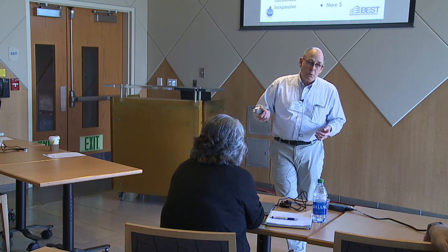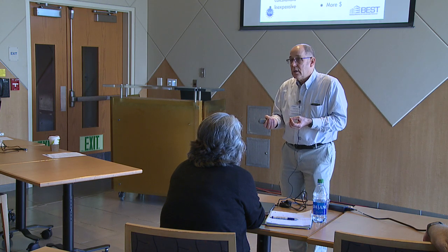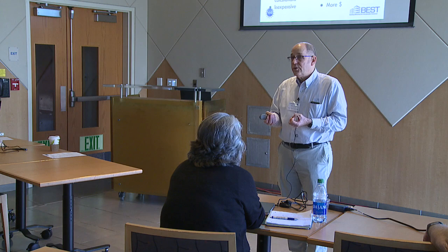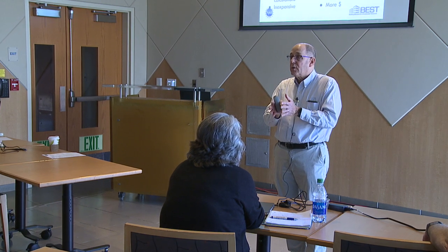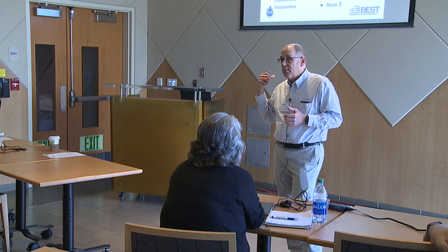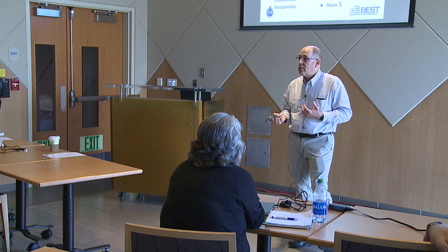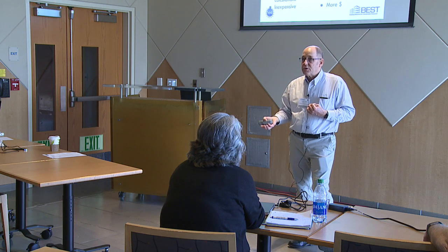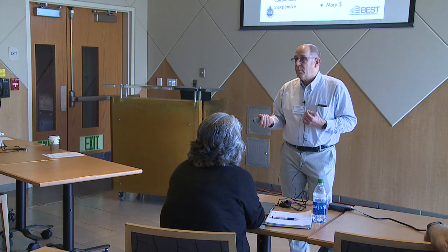We can take a spot measurement for power factor, and guess what? That pretty much does us good. But this was not a project where we were looking at a very specific energy use to guarantee something over time. So it wasn't critical that it was exact, just like what Steve was talking about earlier today. It was all relative, so that's all that really mattered. So amperage is a perfectly fine measurement with a spot measurement of the power factor.